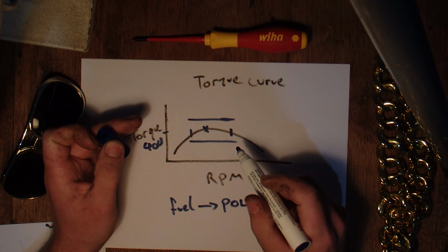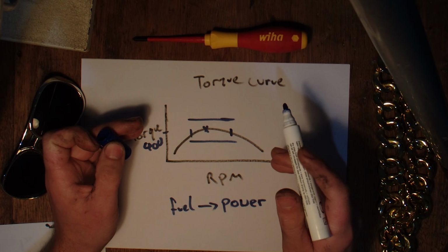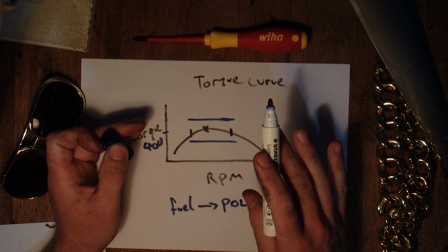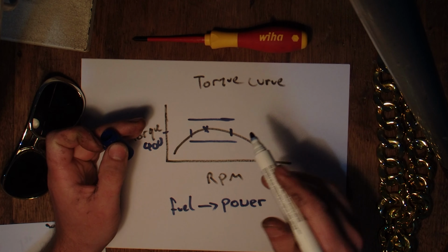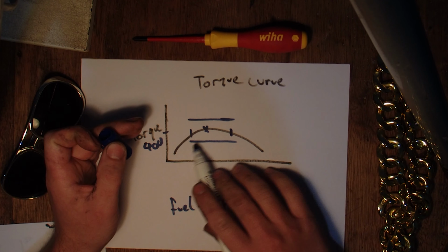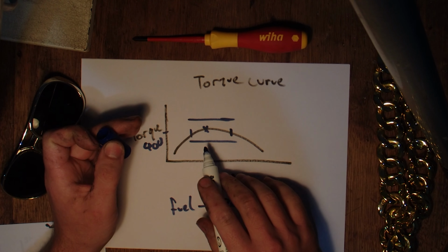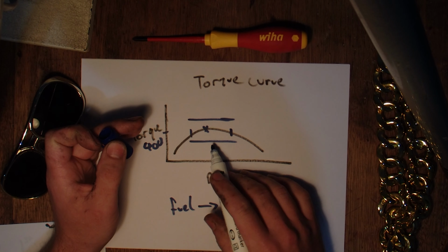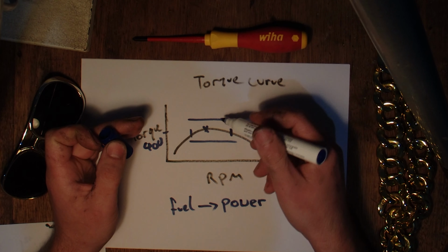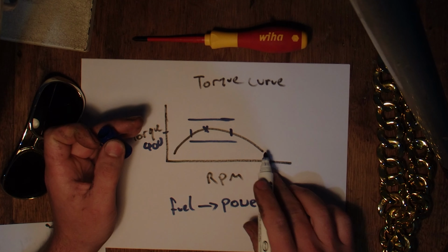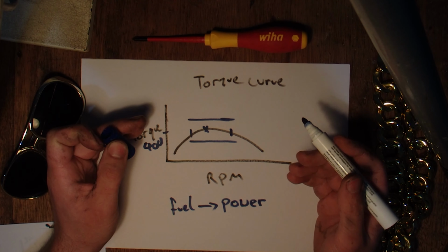If you're really into your efficient driving, what you could do is go to a dyno center and dyno the car where you actually drive the car, so really light throttle. Your torque curve might look like this, or it might look slightly different. Then you would target the highest point of torque to get the most efficiency out of the engine in terms of fuel economy.